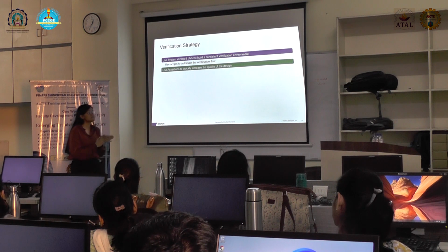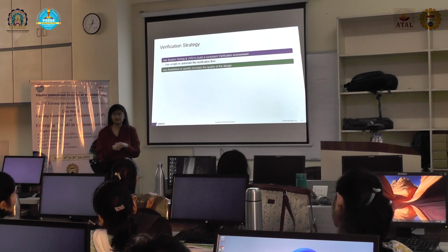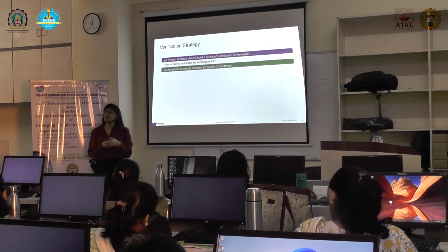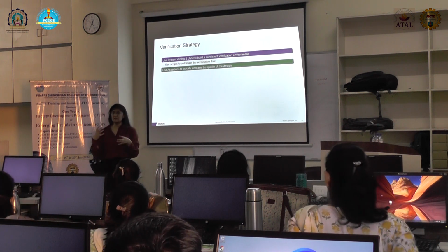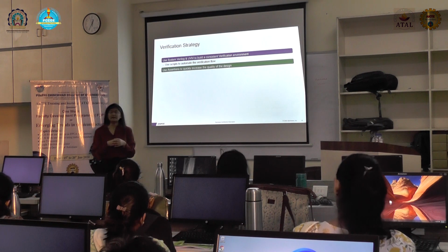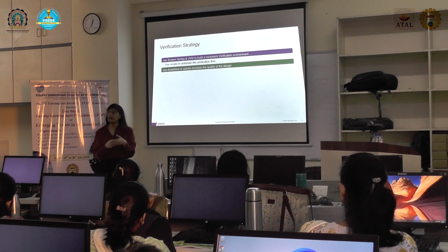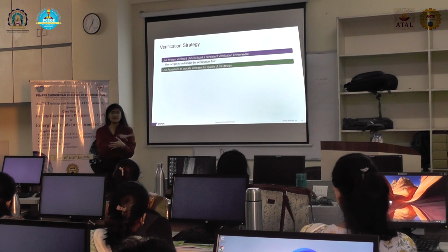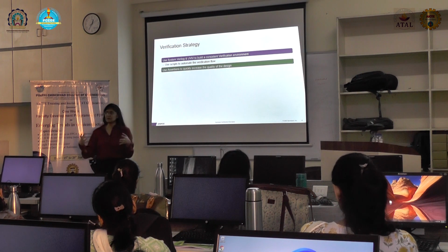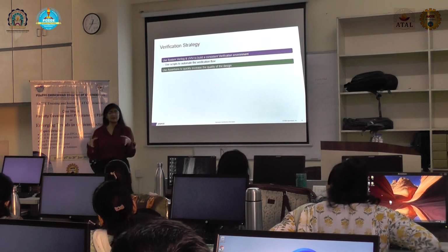Assertions. Assertions are part of verification actually. So assertions, let's say we have signal level interaction between two modules. All information cannot be verified on environment level. Some information needs to be verified prior to environment level. Data integrity checks. What if the handshake between the two modules has not happened properly and we collected data? Data is corrupted, but handshake is itself buggy. So we are wasting time to collect the data and comparing, and a lot of runtime is there, a lot of issues we will face while we are doing this process.